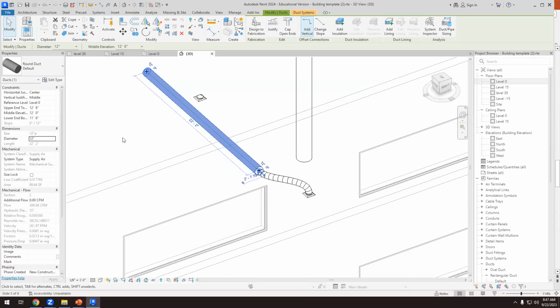And why are we using even numbers? I don't know, but in every single ductwork that I have designed, the company always asked me to use even numbers, not odd numbers. So 9 inches, 11 inches, 13 inches is not an option.